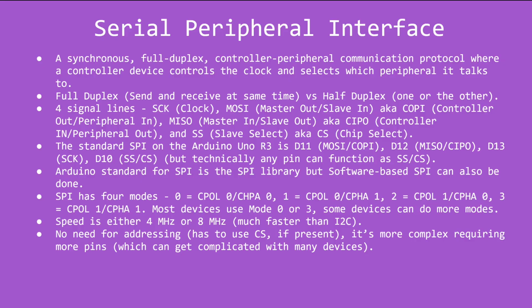It affects clock polarity and phasing. So there's mode 0, 1, 2, and 3. Most devices are going to use mode 0 or 3. Some devices can do more. Pretty much, I think every device has to support at least mode 0, but I'm not entirely sure about that.